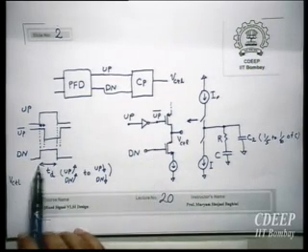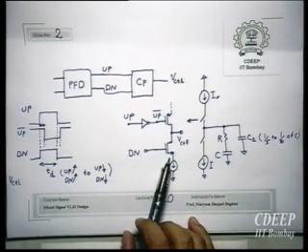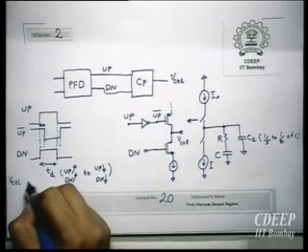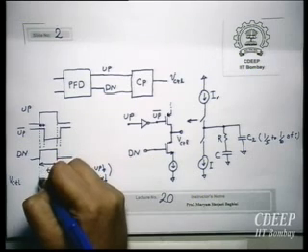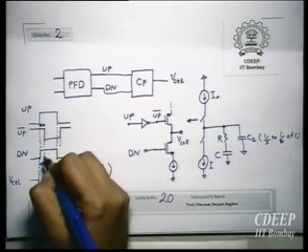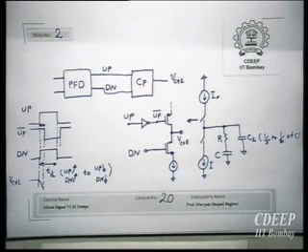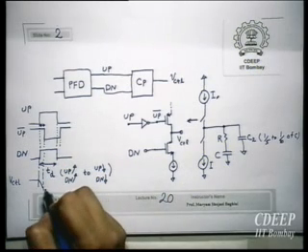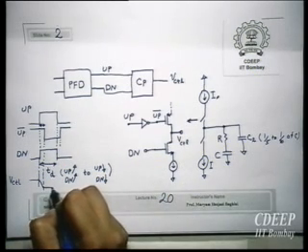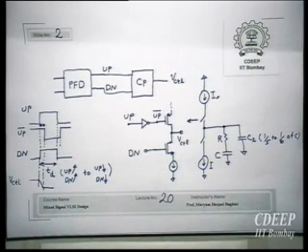Down is high, therefore the second switch is on. Therefore now I have a sink current in this interval, which reduces the control voltage. When up bar is low, both our switches are on, therefore there is no current in the RC network, so the voltage remains as it is.